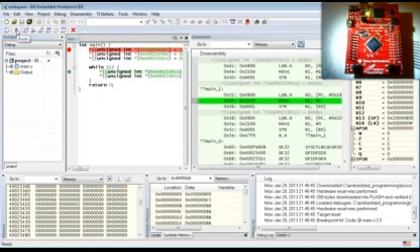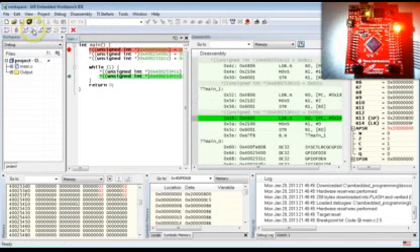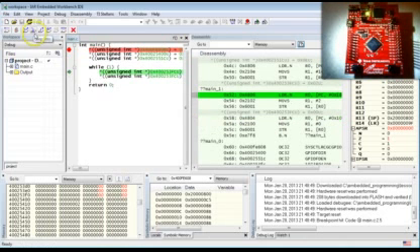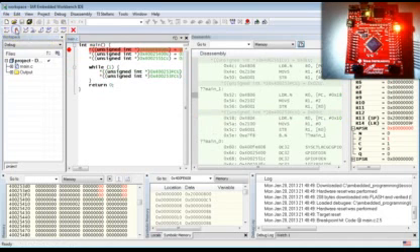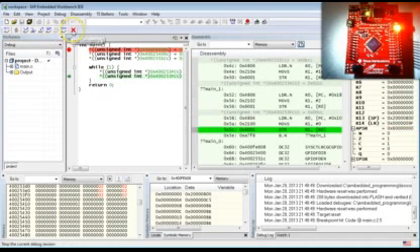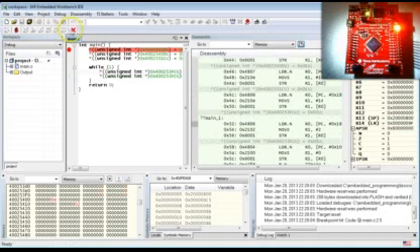Let's break into the code by pressing the Break button and single step again. This time everything is fine, yet when you run at full speed, the blinking stops. Do you know what's the problem here? Yes, you are right. The program just runs too fast for a human eye to notice the rapid blinking of the LED. We need to slow the program down.